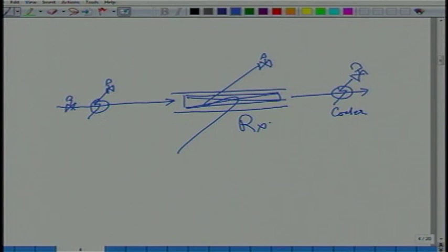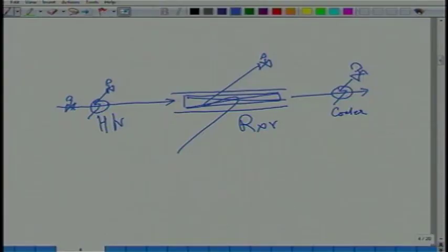Okay, so this is the reactor, this is the heater, that's the cooler. So you can set the flow through this train only at one place, because it's essentially a pipe and there are no drums or surge drums or large hold ups anywhere. This is essentially flow through a pipe. So you cannot put a valve here. Similarly, you can't put a valve here either. Okay, etc. etc. So the feed valve is discounted because throughput is given. Total number of valves is then 1, 2, 3.